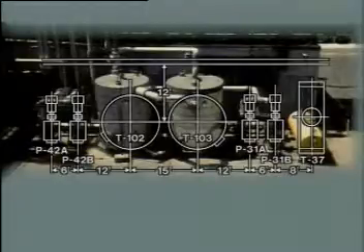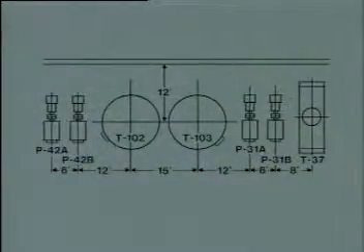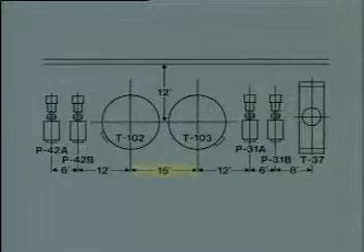equipment they represent. Equipment shown on diagrams is usually labeled with its name or equipment number, or both. For example, a pump may be labeled P31A for pump number 31A. Some diagrams may also show the distances between equipment.